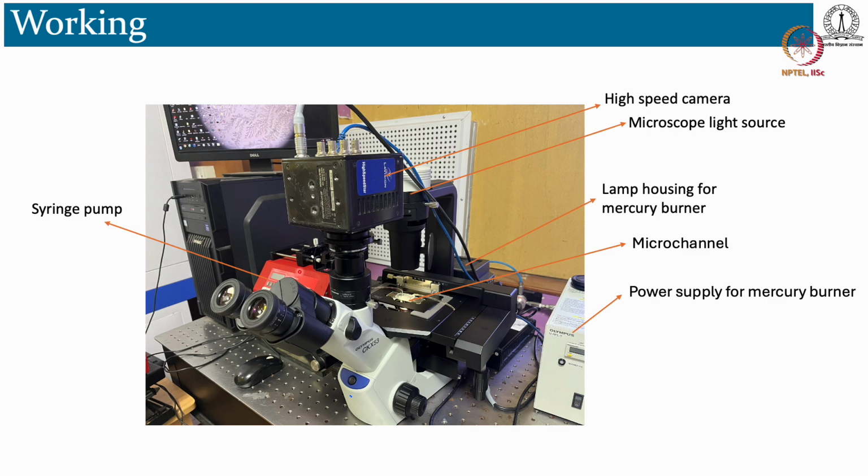So when you actually make the flow inside micro channels, you can seed the particles using a particle seeder, and you can record at whatever rate you want using this camera, which is connected to this PC. Then you can take out the data and process it somewhere in an open source PIVlab or something like that, where you can use the cross correlation technique to get your flow inside the channel.